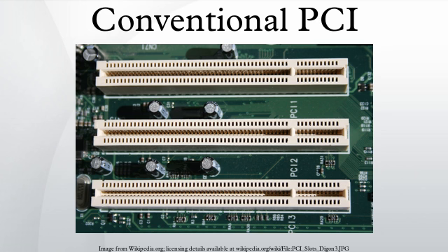If the initiator sees DEVSEL asserted without ACK64, it performs 32-bit data phases. The data which would have been transferred on the upper half of the bus during the first data phase is instead transferred during the second data phase. Typically, the initiator drives all 64 bits of data before seeing DEVSEL. If ACK64 is missing, it may cease driving the upper half of the data bus.